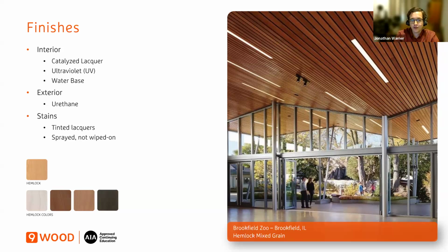Stains are applied in our industry in two basic ways. If it's a lighter stain, it can often be put into the interior coatings, so it's applied at one time. If it's a darker stain, then it will be applied first, dried, and then the finishes will be applied after it, usually through some type of finishing line and equipment. Manufacturers should be able to provide not only standard stains, but custom stain matches to any control you have, if you're matching millwork or a particular design intent. They should be able to provide that in any color, which can be very important.